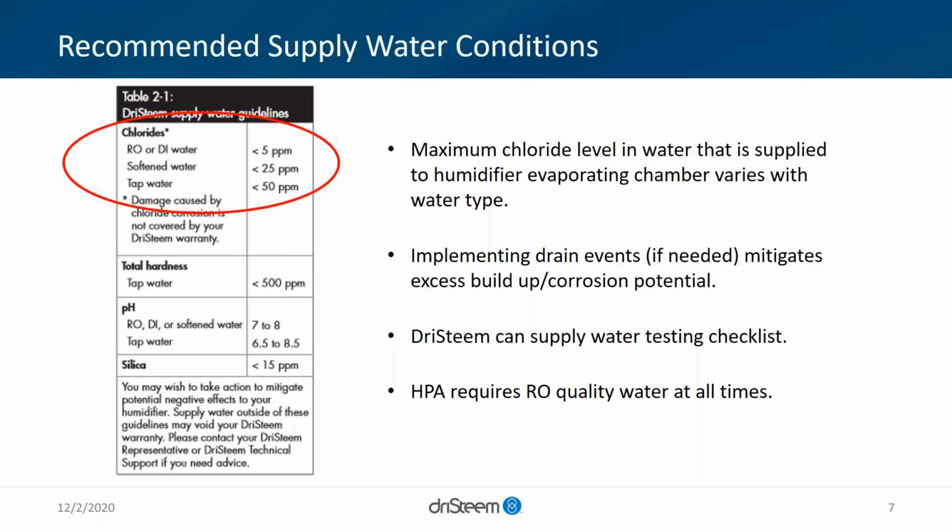So, recommended supply conditions. This is different for each piece of equipment. It's different for humidifiers versus steam boilers, whether that's a fire tube or a water tube, different than cooling towers, different than a lab's need. But really here, we're looking at what we need to get to satisfy that inlet condition. This is an example of a humidifier required water type.